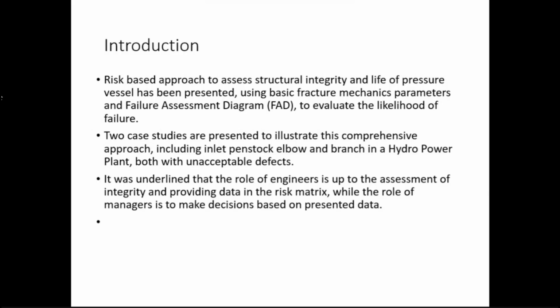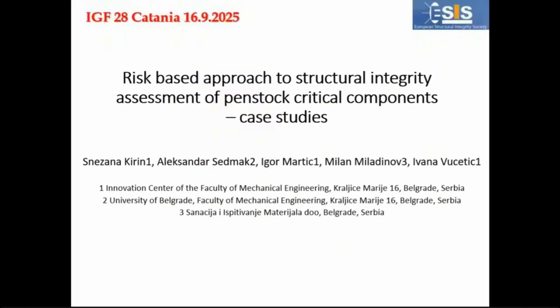Risk-based analysis here is reduced to engineering assessment using some basic equations of fracture mechanics, or, in the case of slightly more complex geometries, finite element method analysis and application of its results. A failure assessment diagram is the tool that we use to get this risk assessment, which we present in the form of a risk matrix.